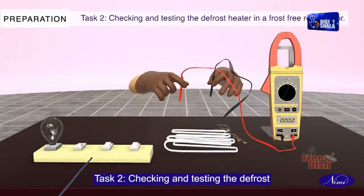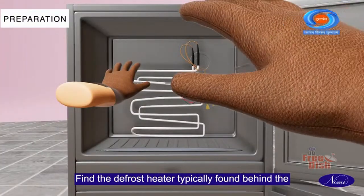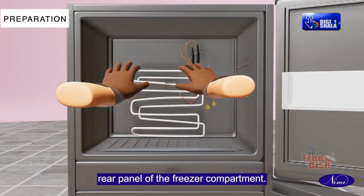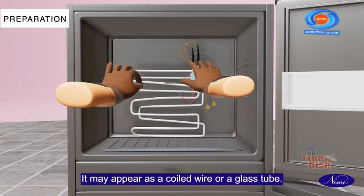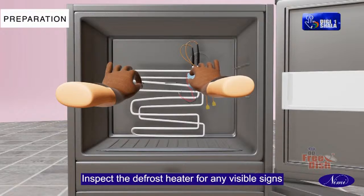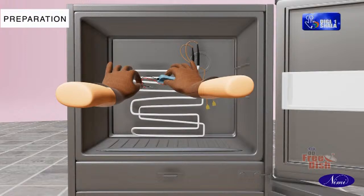Task 2. Checking and testing the defrost heater in a frost-free refrigerator. Find the defrost heater typically found behind the rear panel of the freezer compartment. It may appear as a coiled wire or a glass tube. Inspect the defrost heater for any visible signs of damage such as burns, breaks, or discoloration.